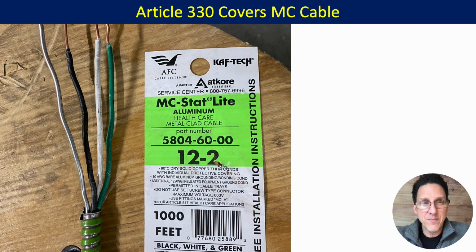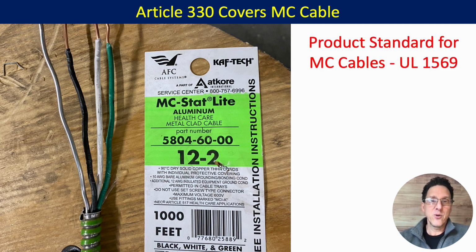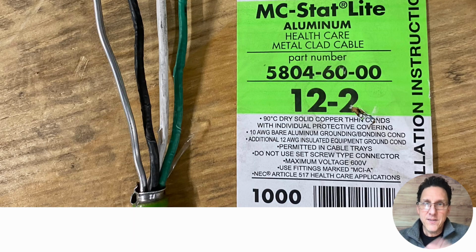Kind of weird, right? Apparently it's fine on MC, but not AC, even though the jackets are pretty much identical. Different product standard, though. The product standard for MC cable is UL 1569 versus UL 4, right? If you look closer at the tag, this is MC cable. It doesn't say anything about not for use on DC circuits, right? Nothing.